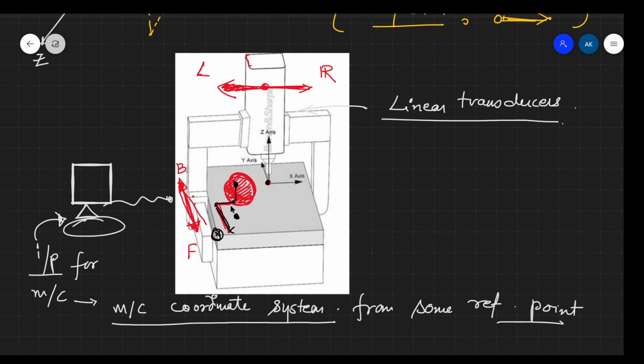where all these measurements will be done, and those data can be put in this machine, and the probe end will go to this. Now for different values that you feed in the machine, this probe head will touch different points on the job, and different points will be relative to each other.